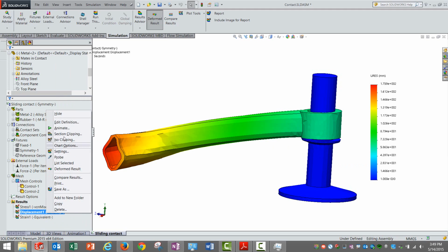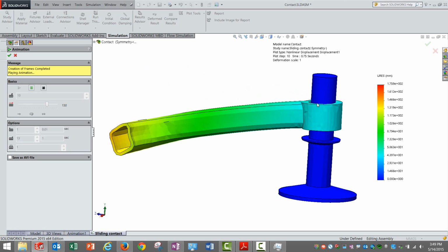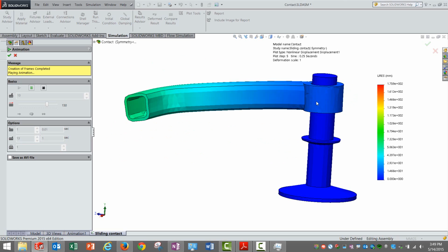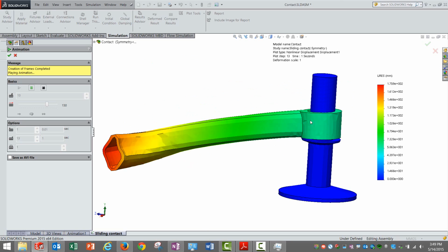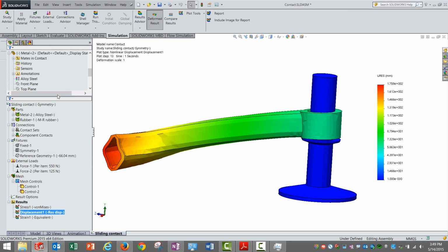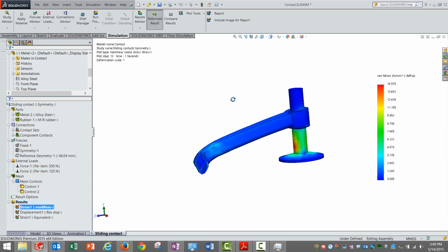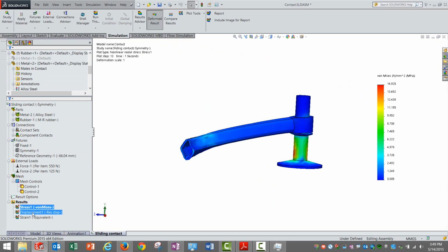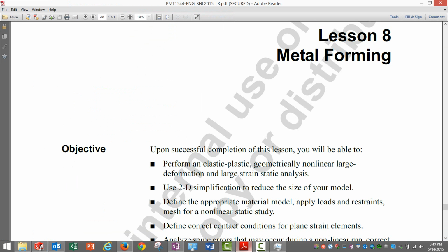If you see the results here, and if I animate, obviously the 66 unit displacement that we give is helping to stabilize the setup. It is taking this part down, and that helps in solving. Otherwise, all other results are typically mesh, stress, displacements, etc. So this is what I would like to cover in this chapter. If you continue to face any convergence problems, please approach me. I'll try to help you out with the right settings.